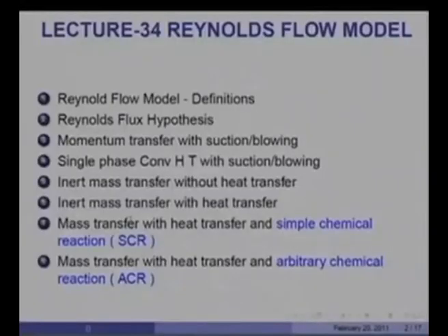And what I will do is first of all define the Reynolds flow model again, go over the Reynolds flux hypothesis. The Reynolds flow model is supposed to mimic the boundary layer flow model. We will also consider momentum transfer with suction and blowing. We will also consider single phase convective heat transfer with suction and blowing, and then the four types of mass transfer problems in which the species mass transfer equation as well as the energy equation will be invoked.